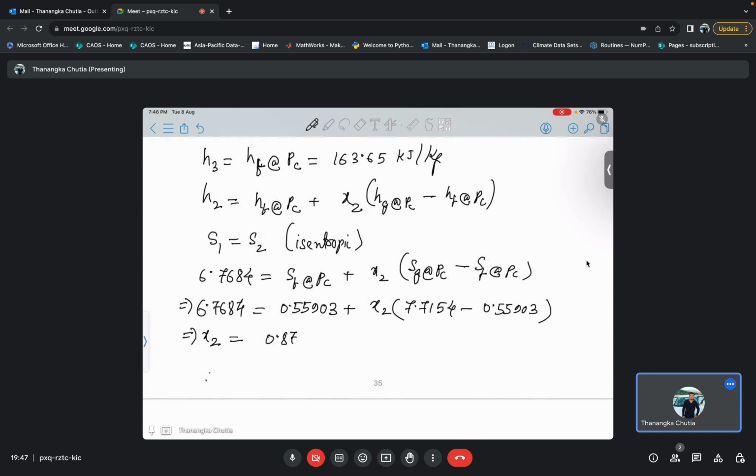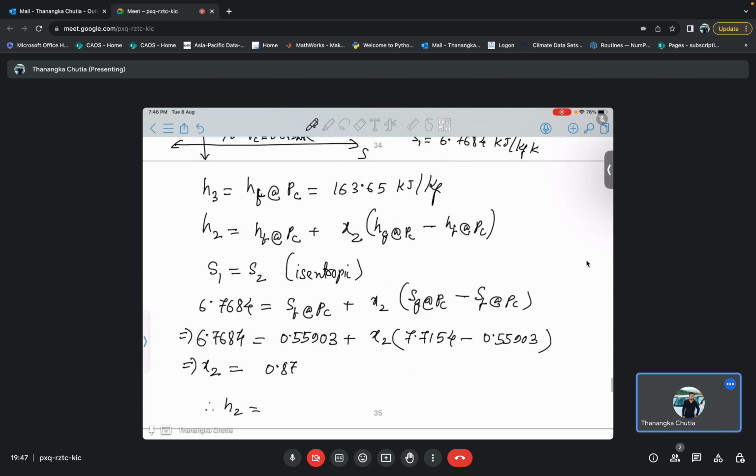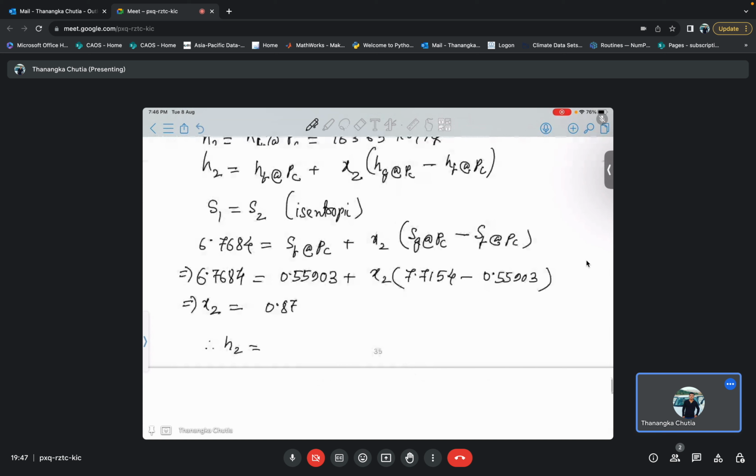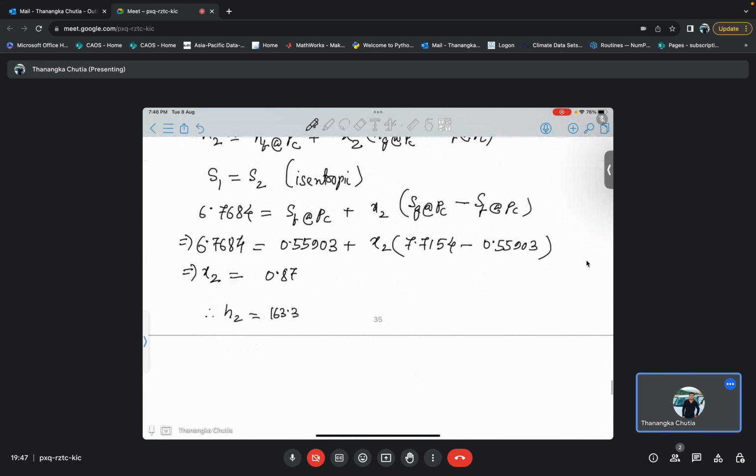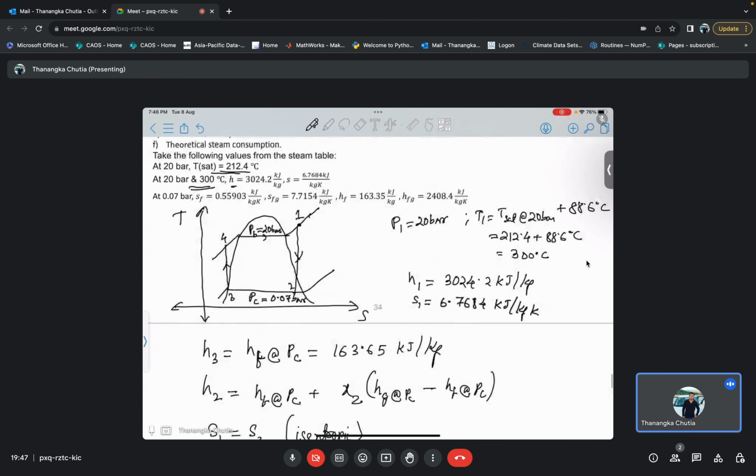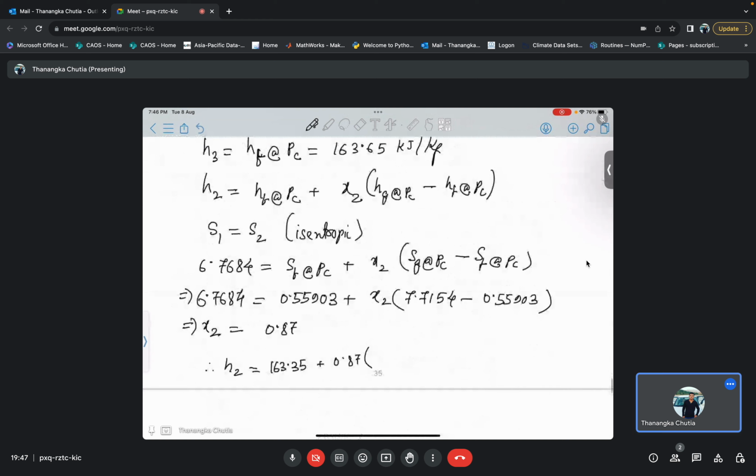Therefore my H2 will be Hf at Pc, 163.35, plus 0.87 times Hg, 2408.4, minus 163.35.